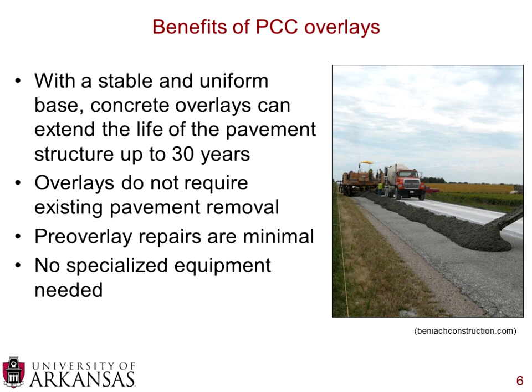What are some benefits of PCC overlay? One of the key points to PCC overlays is you need a stable and a uniform base. Just like really any pavement strategy, what lies beneath is just as critical as what is on top. So if you have a stable and uniform base, PCC overlay should be able to extend the life of the pavement up to 30 years.